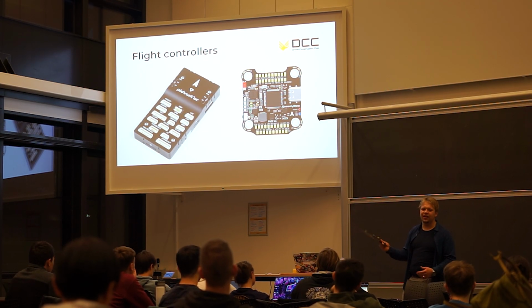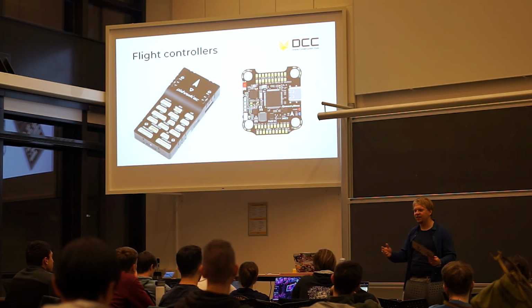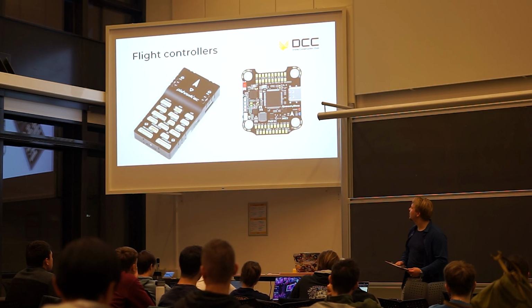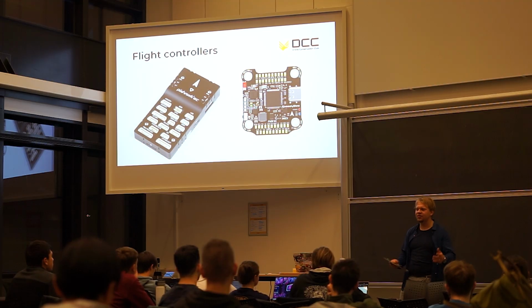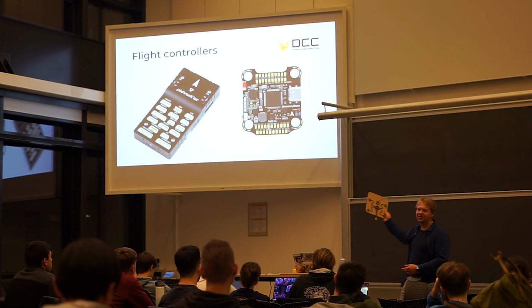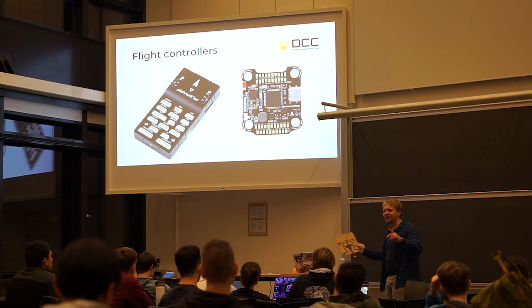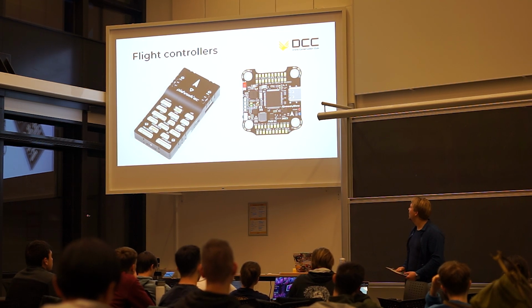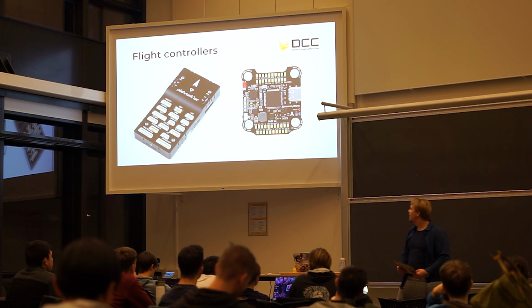These boards burn as well. That is another thing. Sometimes you can feel what burns. Quite often it's the regulator or the processor itself. If the processor burns, you can touch it. It's really hot. That's kind of a done deal.